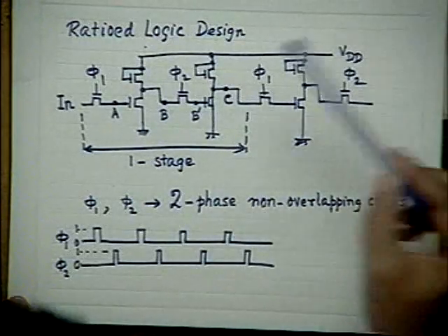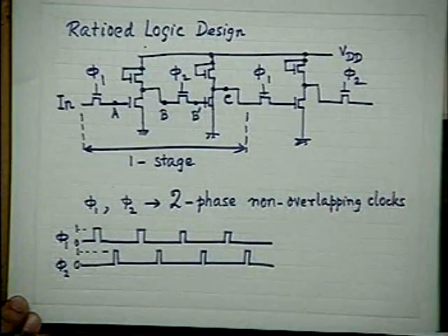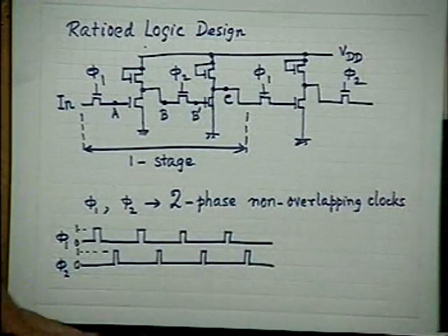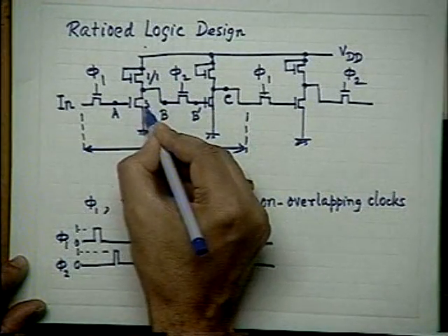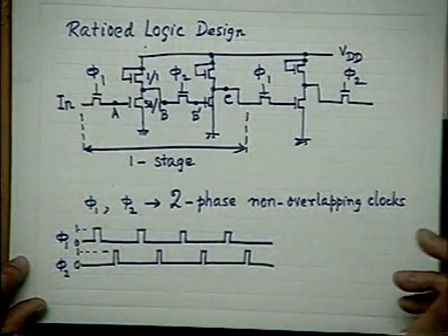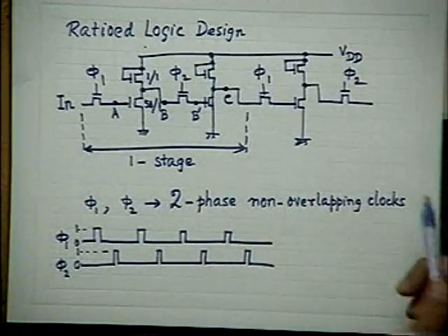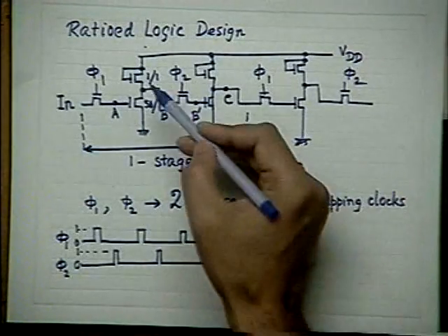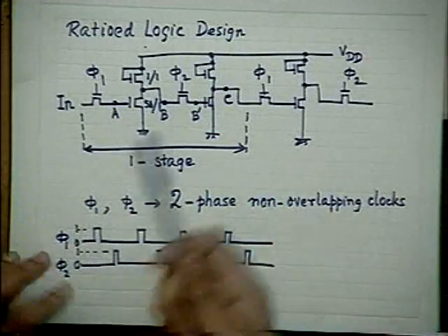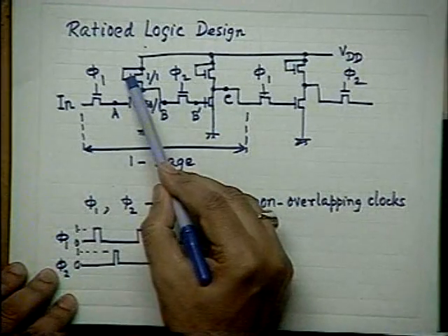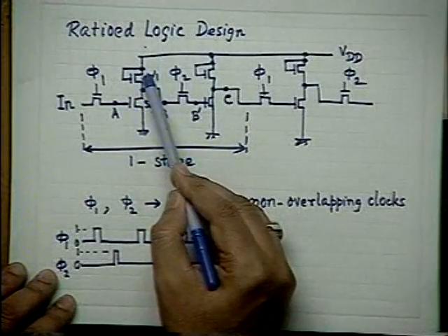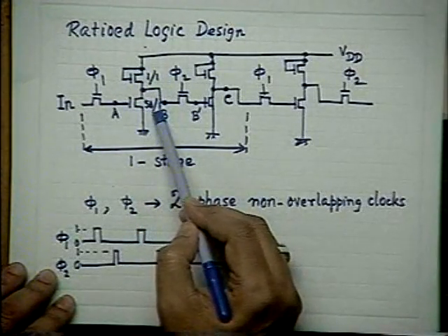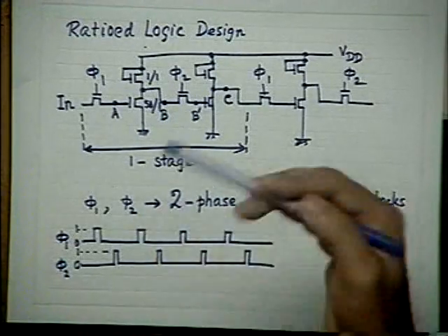And this is why it is called ratio logic, because these inverters are standard inverters, there is nothing new. For this kind of configuration I have to maintain a ratio like 1:1 and say 50:1. These are standard. And if you use the HMOS principle where this transistor is a depletion mode, then simply you connect it here, and this may be 1:1, but this will be around 5:1 or 4:1. There will be some saving.